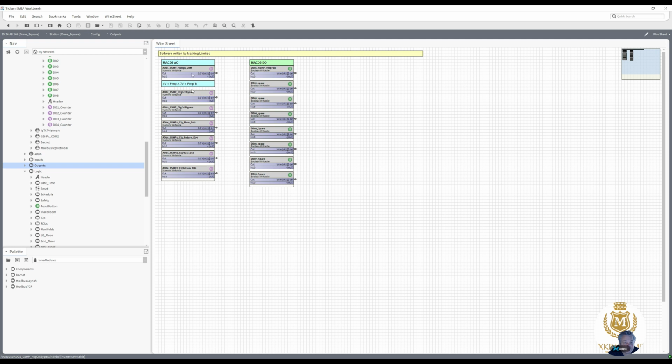And then we already know that that is 4 volts to run pump A and 7 volts to run pump B. 0 volts turns them off. So I've got to put these points into the logic, but first of all I need to now do the Modbus from the ground source heat pump 1 and 2.